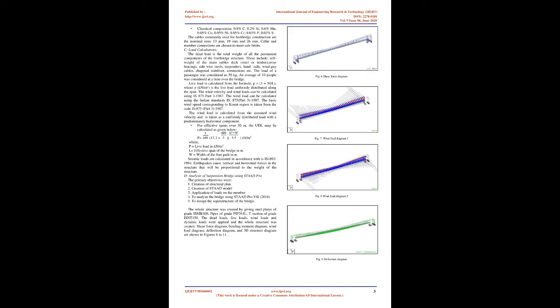Suspension bridges tend to be the most expensive to build. A suspension bridge suspends the roadway from huge main cables, which extend from one end of the bridge to the other. These cables rest on top of high towers and have to be securely anchored into the bank at either end of the bridge. The towers enable the main cables to be draped over long distances.